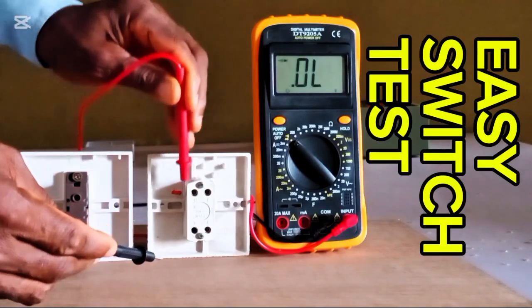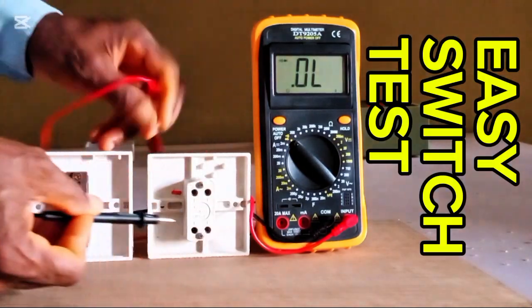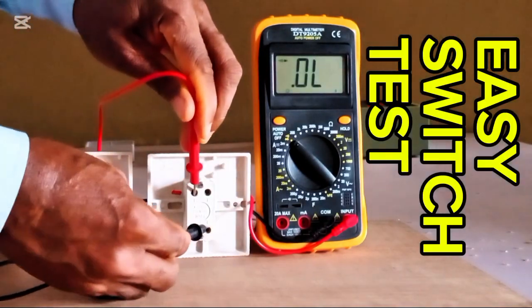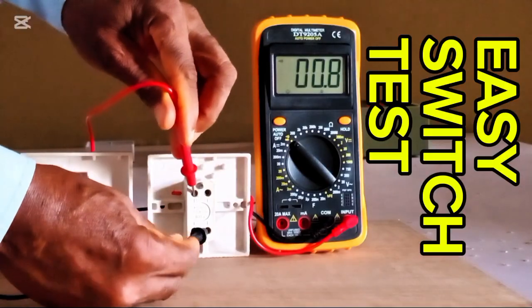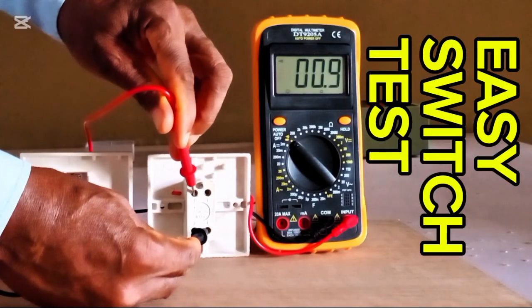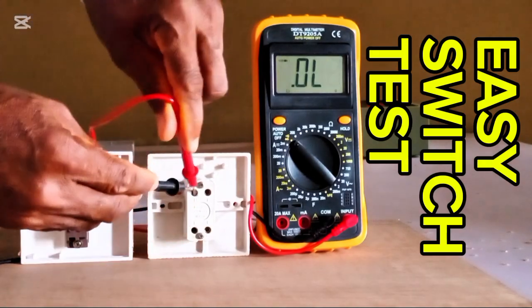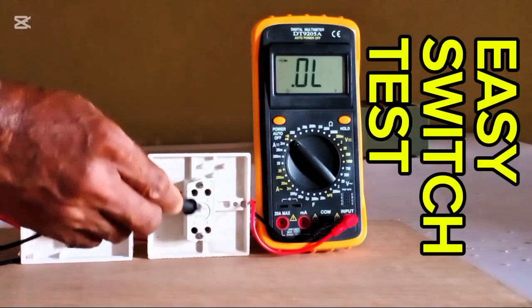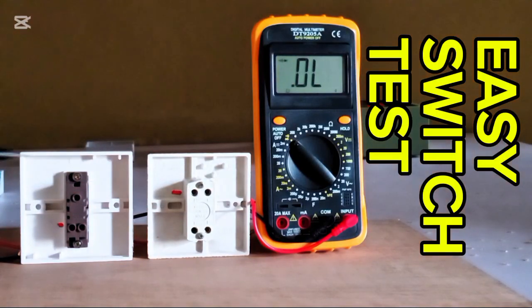All right. Now we can see. Good. Let's see. Good. The diagonal is meant to read here. Suppose it failed to read in the flip. When we flip it and it fails to read, it means internally, that is to say, terminal line 1 to 4 has a breakage internally, or open circuit, and that is why we never read.